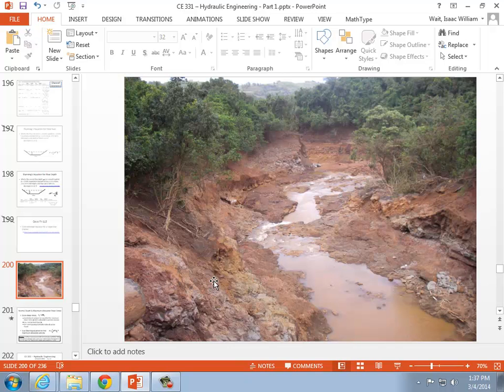So let's say in the second part of the problem, what channel width is needed to get the flow depth less than 1.5? Having it all typed in symbolically would allow you to edit the equation so that now the unknown is going to be b, and then you'd be given y is 1.5. And so it gives you flexibility, is the advantage of using symbols instead of numbers. Also, as you're typing the equation, it's a little bit easier not to lose track of where you're at if you're using variables instead of the numbers.